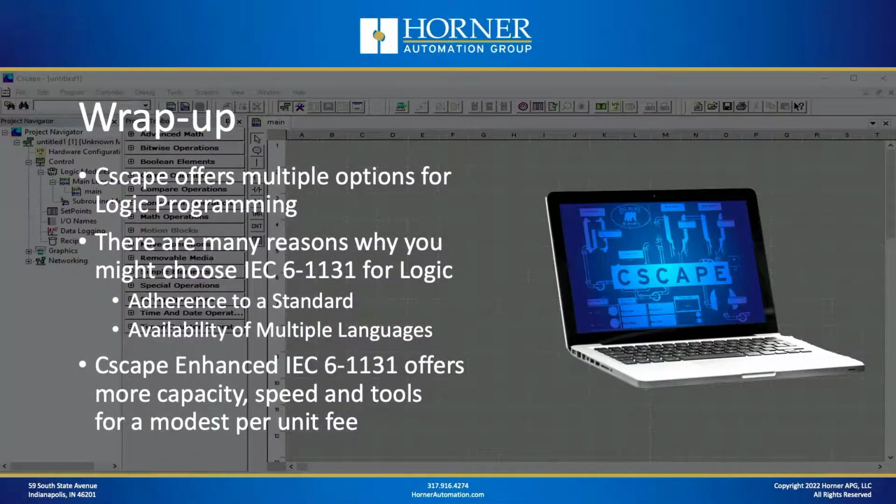Let's go ahead and wrap up our topic. We talked about the fact that Cscape offers multiple options for logic programming, including IEC 61131. We talked about the reasons why you might choose IEC 61131 for your applications. Maybe the adherence to a standard is important. Maybe it's the availability of multiple languages. We also talked about the availability of enhanced IEC 61131 in most OCS models, but not the micro OCS. Enhanced IEC 61131 offers more capacity, more speed, and more tools, but it does require a modest per unit license fee.